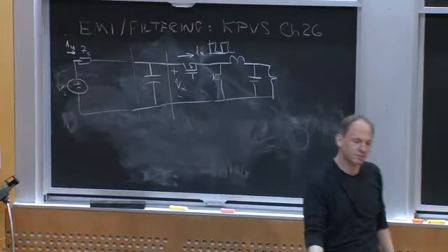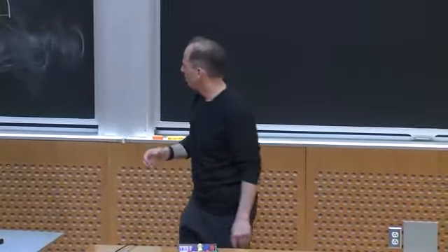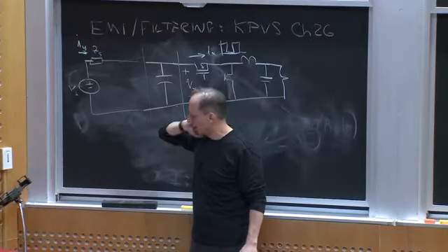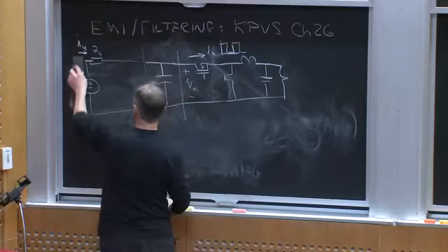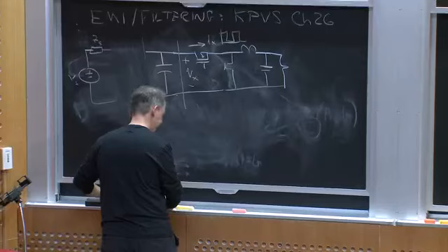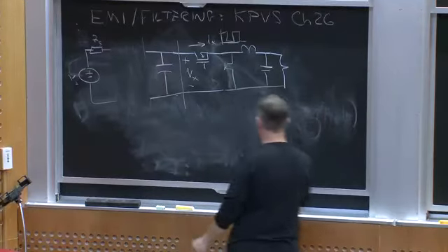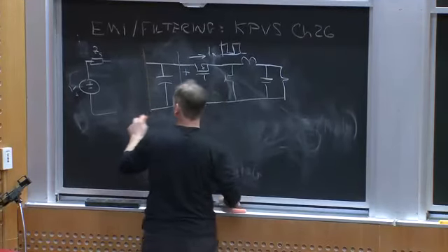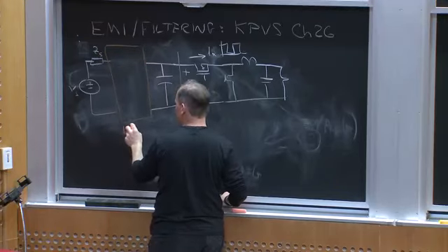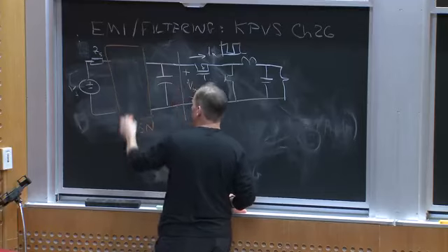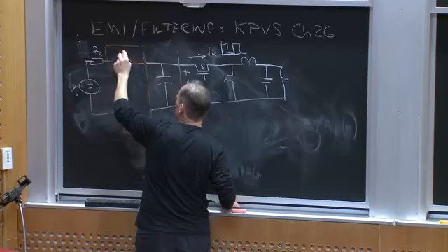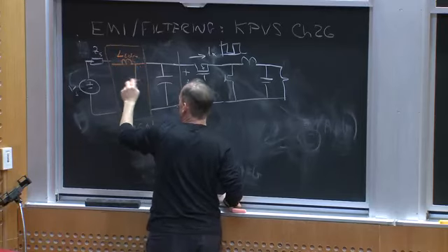So if I want to test to some standards, I need some better way of basically controlling the impedance we're looking back into. To do that, when we're doing EMI testing alone, we insert an additional stage in here, which I'll draw in orange. It would look something like this. I'll have some box that is part of my test setup called a LISN, Line Impedance Stabilization Network.